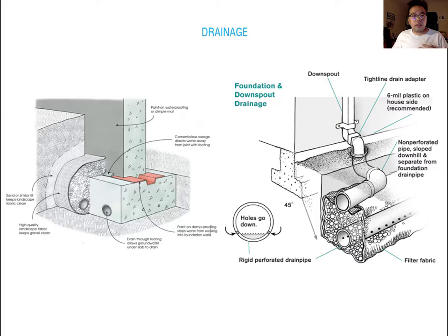So let's talk about the foundation assembly detail. In the first one, you can see the concrete retaining wall and the footing here. Over the concrete, we usually add a drainage mat and waterproofing membrane, and you can also see two different drainage pipes. The drainage pipes are covered by aggregate. One is a perforated drainage pipe, and the second one is a solid drainage pipe.